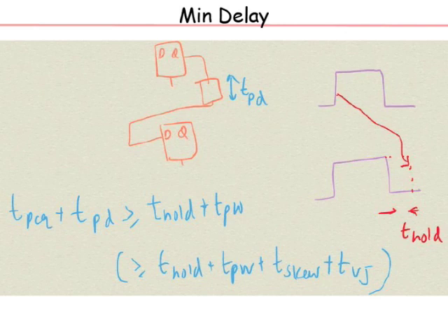So increasing pulse width allows you better skew tolerance and borrowing, but then it has this problem that it will degrade the hold time problem. So that means you have to put more delays out here. What does putting more delays mean? You have to put more buffers. It increases the area overhead, increases the power overhead. Okay.